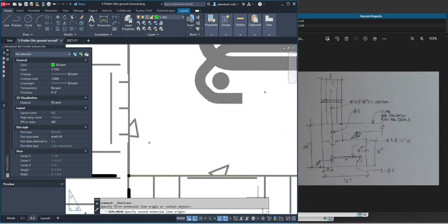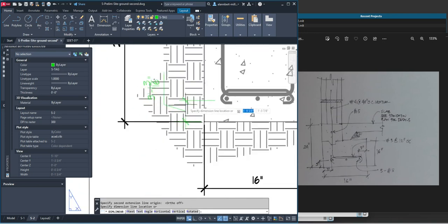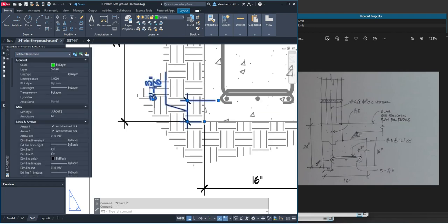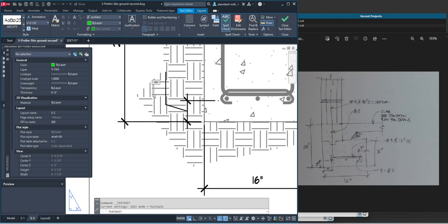I'm just gonna remove my O snap. Is this one? No. O snap. Show snapping reference. Where's my O snap? I don't have my keyboard, so I'm just gonna put it here and drag it here. And then you can also force this: double click and delete that and force this to say 3 inches. Press enter. Oh, no, press outside. There you go.